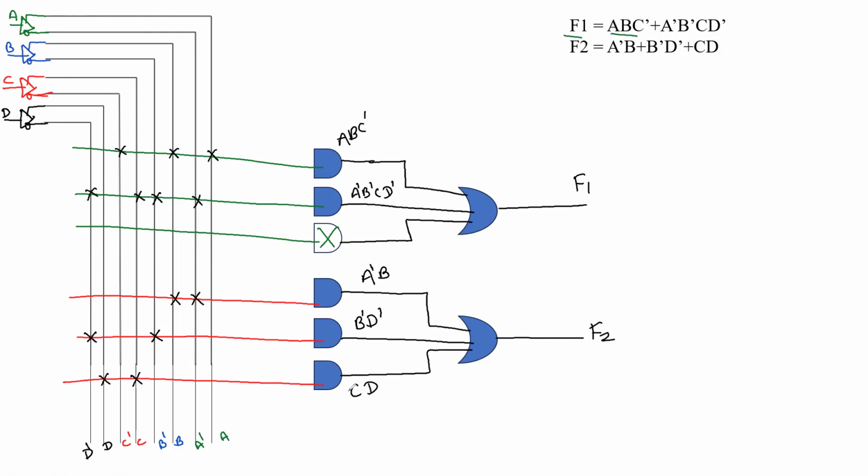So finally, in this programmable logic device, first we have seen the PROM. In the case of PROM, the first block is the fixed AND array, or we can have a decoder, and the second block is the programmable OR array. In the case of PLA, both the AND array as well as the OR array are programmable.